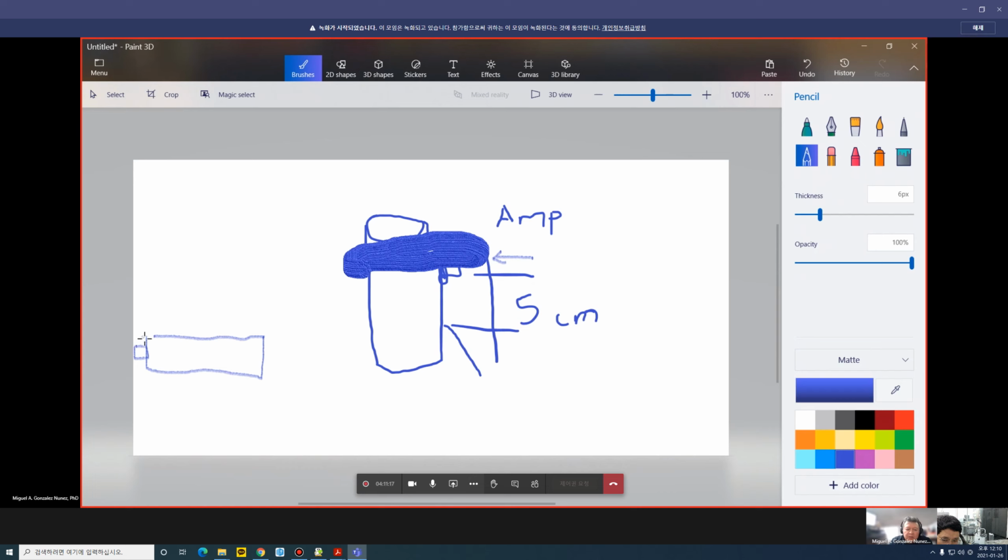When you have your sensor and you perform the pencil lead break again at 5 centimeters, this is our reference point, right? Yes, that would be the reference, because in this situation we are controlling everything. But this is your real situation. Yeah, that's right. So far I understand.